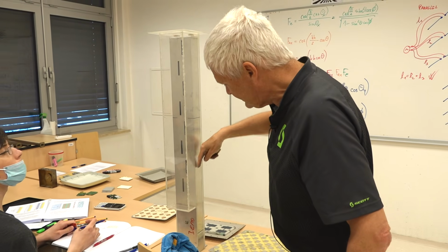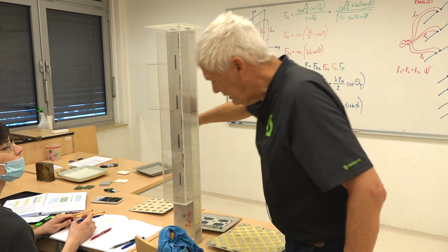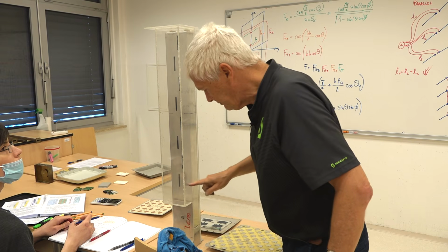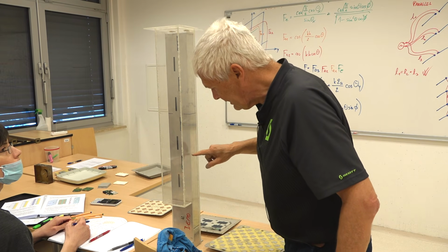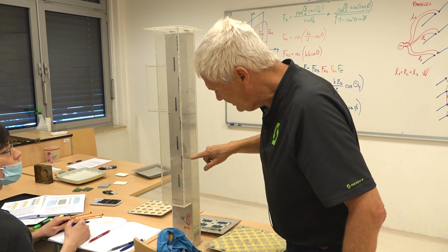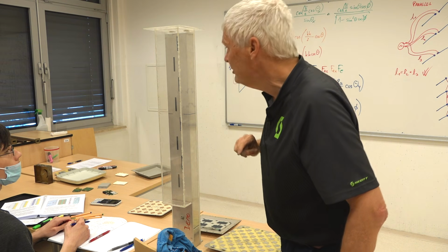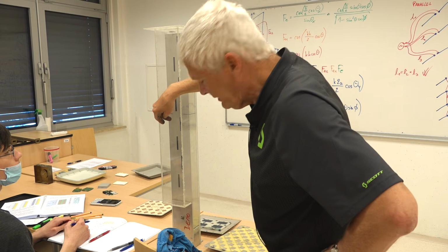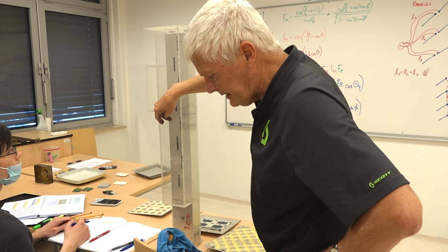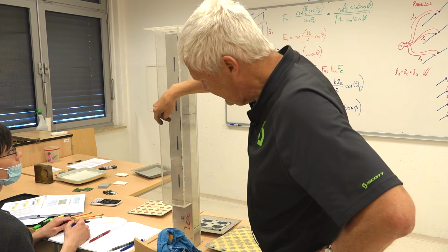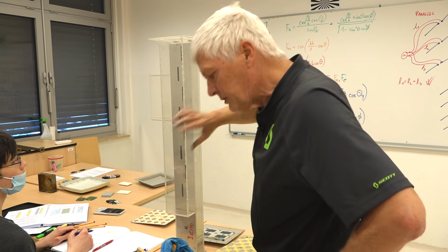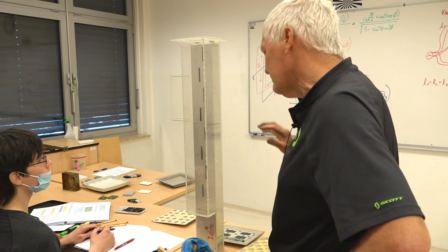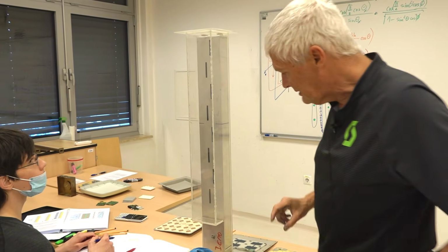So the waveguide has some current flowing on the side walls, and this current actually feeds this dipole, this dipole, and so on. With the eccentricity, if you had the dipole exactly in the center of the waveguide, it would receive nothing. With the eccentricity of the dipole, you adjust how much current a particular dipole has.